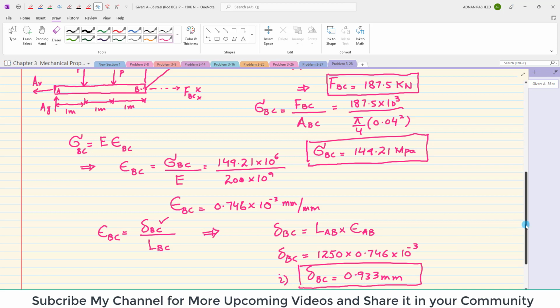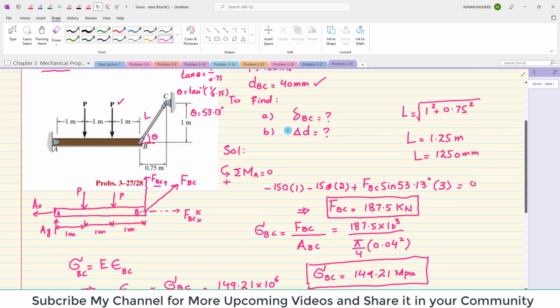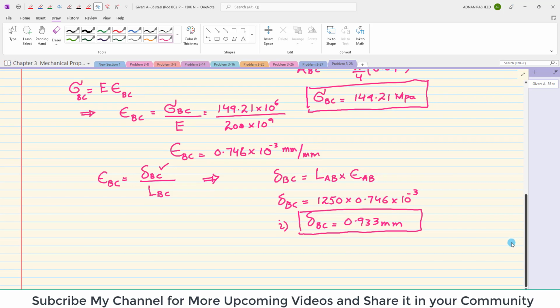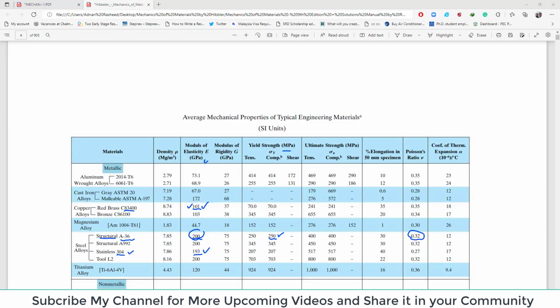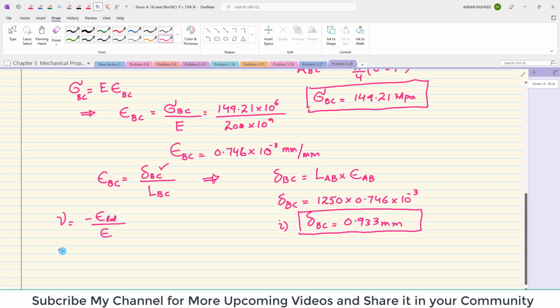Now we will move towards the second part. In the second part, it has been asked to find the change in diameter. Clear? So for change in diameter, we will use this formula: Poisson's ratio is equal to minus lateral strain divided by normal strain. We have normal strain, we do not have lateral strain, and the value of Poisson's ratio can be found from this table. So 0.32. This is the Poisson ratio.